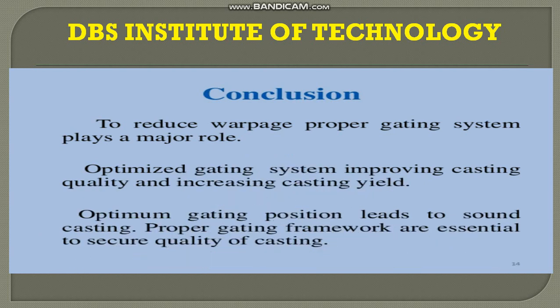Now this is the conclusion. To reduce warpage, a proper gating system plays a major role in the castings. An optimized gating system improves casting quality and increases casting yield. Optimum gating position leads to sound castings. Proper gating frameworks are essential to secure quality of castings.